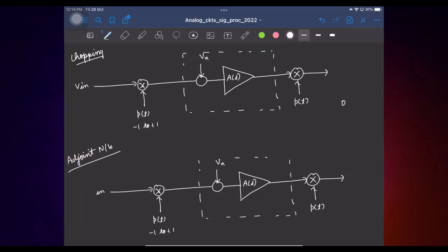So what happens? I'll basically apply the input this side. So signal directions all change. So this is like a multiplier which imparts time varying gain. So this becomes P of minus t, and the signal flow also changes. You can think of this as a voltage controlled voltage source with this gain. Now it becomes a current controlled current source with everything flipped.